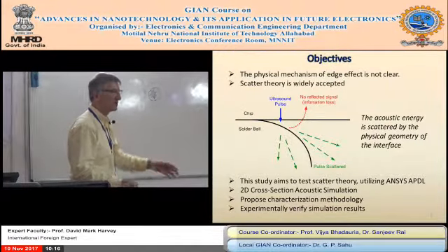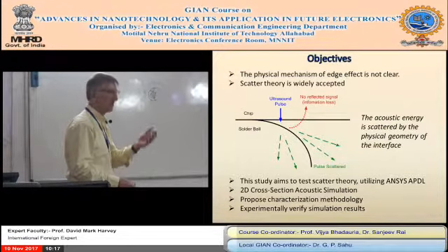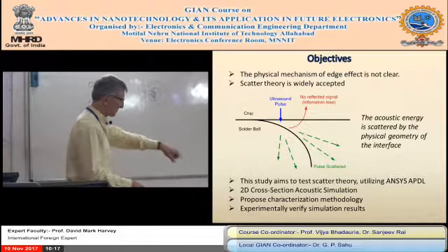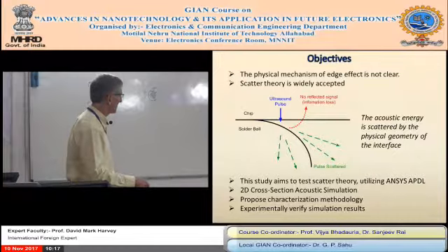couple the ultrasound. So water gets in. We don't want any air bubbles. Air bubbles will reflect the ultrasound and give us a false result. So we have a squeezer. We might go around with a little water squeezer, get all the air bubbles out from everywhere.